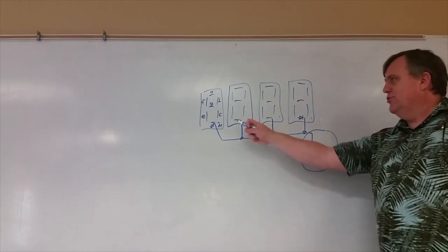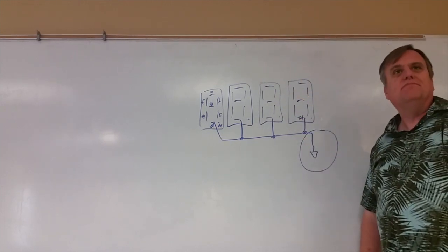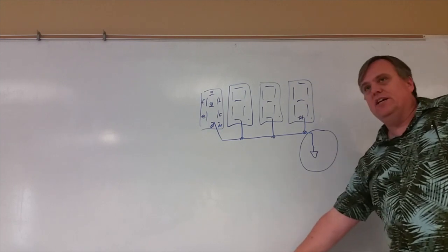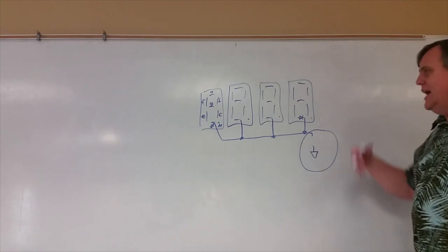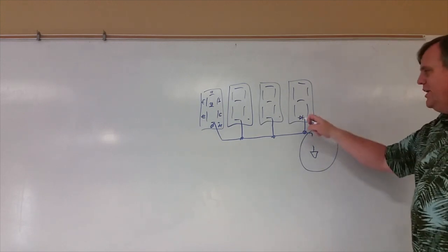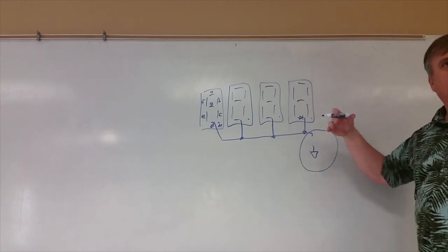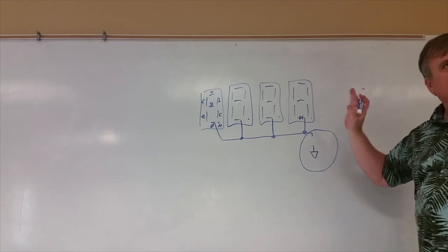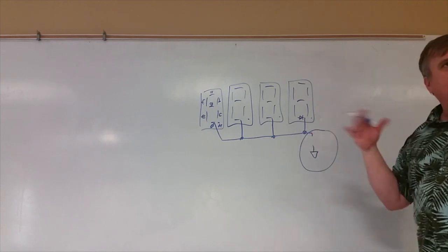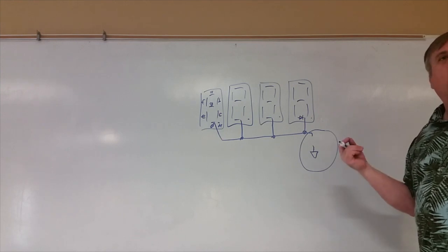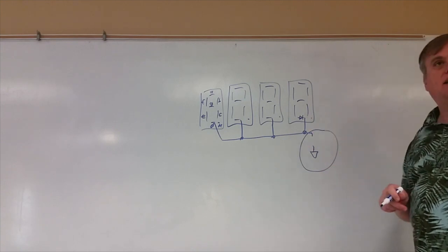So we're going to handle not making them all light up at the same time by handling the other side, the positive supply. I need a resistor. Why do I need a resistor? Current limited. Yeah. Otherwise, I've got 3.3 or 5 volts running across this little diode, which is going to take, depending on whether it's germanium or silicon or whatever, anywhere from 0.3 to 0.7 volts as a drop. Let's say it was 3.3 volts, and let's say it was germanium, right? So it's 0.3 volt drop. That means I got 3 volts over essentially no resistance. The current's going to spike and that LED will burn out.